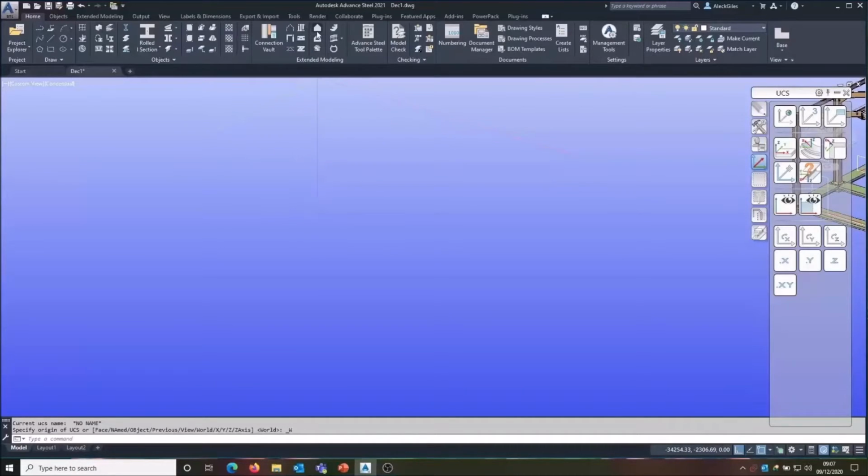So first of all, let's do a rectangular area. We're just going to use the define area command. The first question is, do you want to select supporting beams? I'm going to say no on this first instance. Then I'm going to say I want a rectangular area, and just draw a rectangle. If I want any openings, then I'm going to go to define cladding opening. Obviously you can skip this if you don't need any. Again, I'm just going to say it's rectangular.